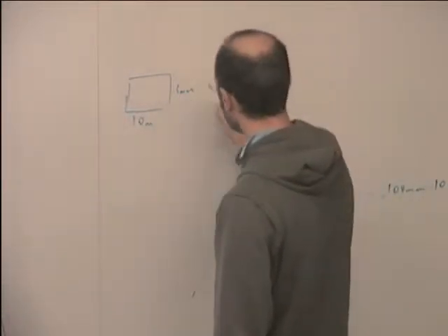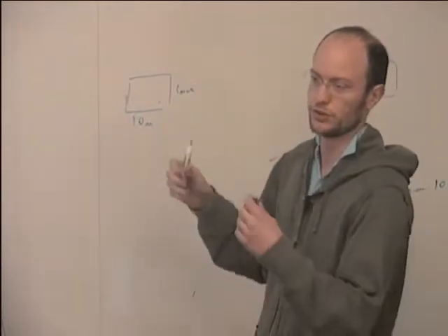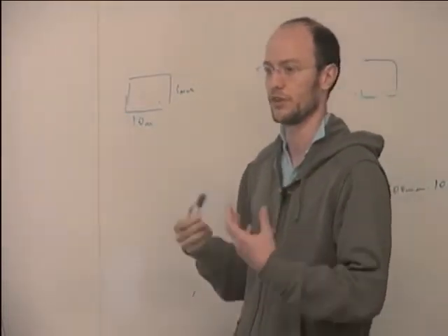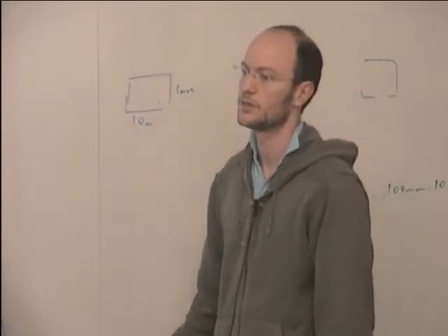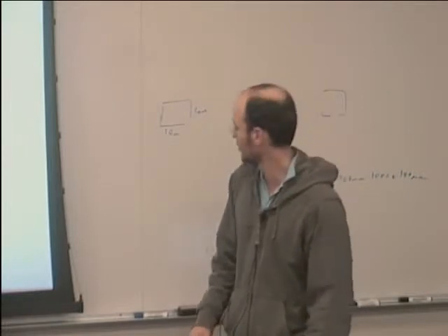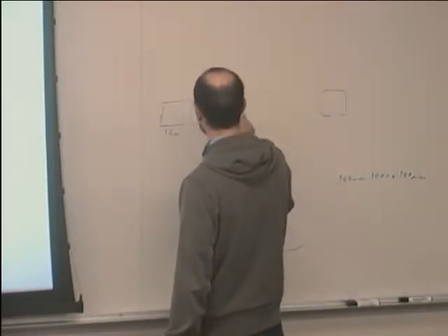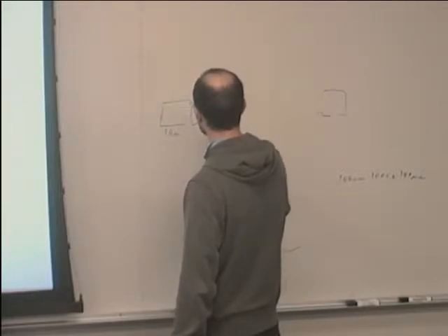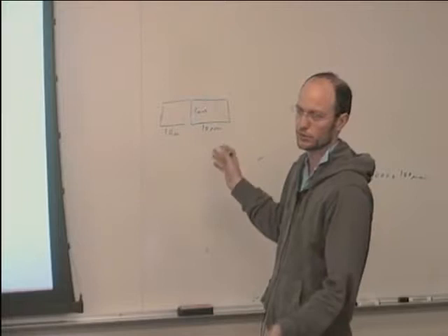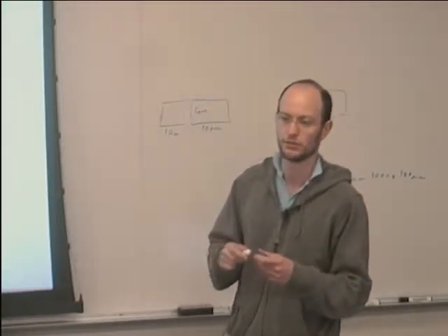And so you need to go across 10 gates for the wire resistance to start being significant. So this is just to have an idea. If you're just routing from this gate to the next, then the resistance will not make too much difference because you're going only like 10 microns or so. Unless you route in polysilicon, then it'll be okay.